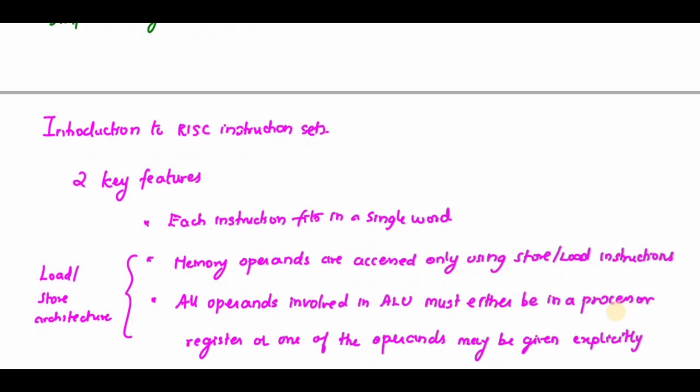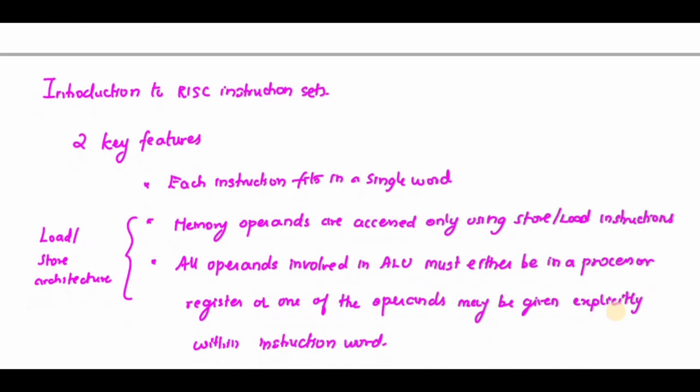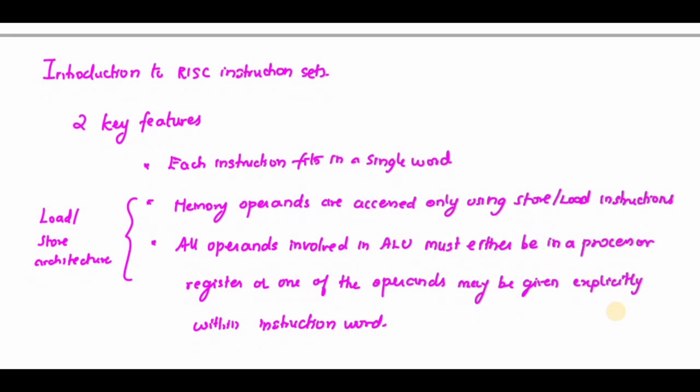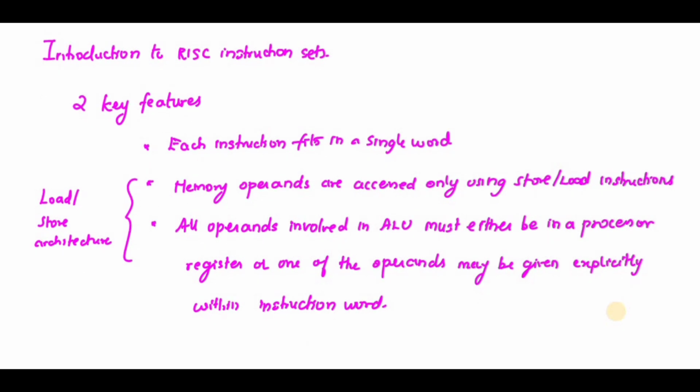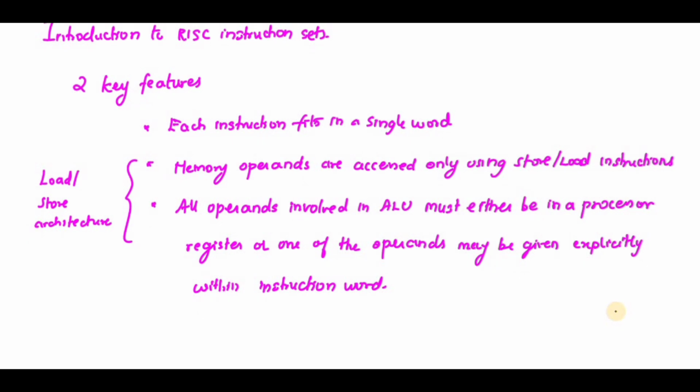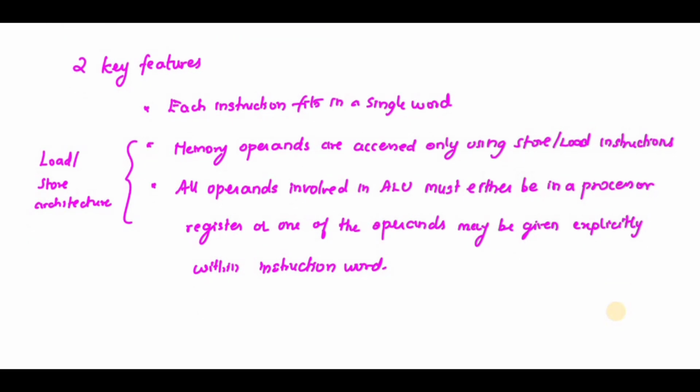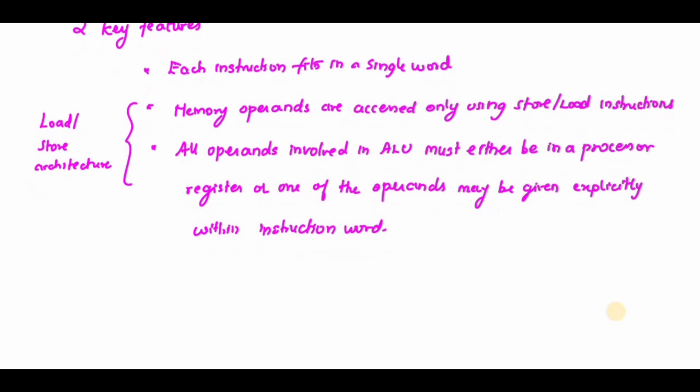Instruction sets. It has two key features. One is each instruction will fit into a single word. Next, it will use a load store architecture. That is, the memory operands are accessed only using store and load instructions, and all the operands involved in the arithmetic and logical unit must either be in the processor register, or one of the operands may be given explicitly within the instruction word.